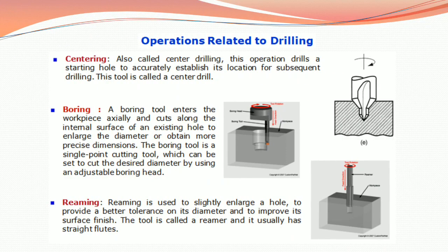Operations related to drilling. First one, centering. Also called center drilling, this operation drills a starting hole to accurately establish its location for subsequent drilling, and this tool is called a center drill.